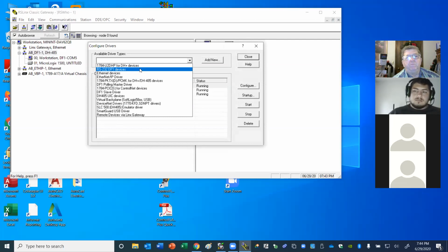What does it mean by the DH-485? I kind of remember one I did over there by the Singer on the kill floor, and I chose one of them. I auto configured it and it communicated. I didn't think I chose the RS-232. Right. It's Data Highway 485. It's a different protocol. Will it work though? Victor used that one. I mean, it worked, right? Apparently.